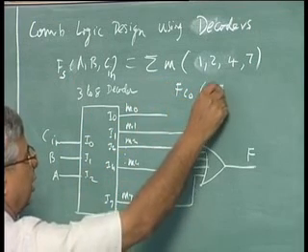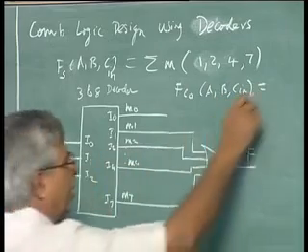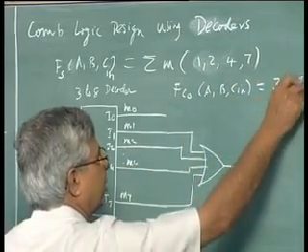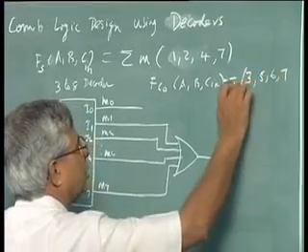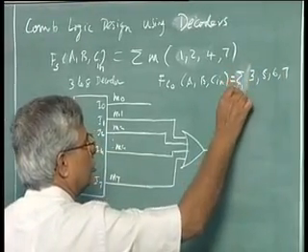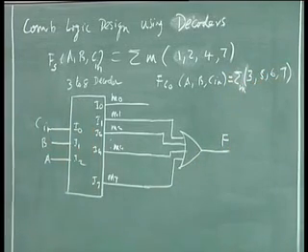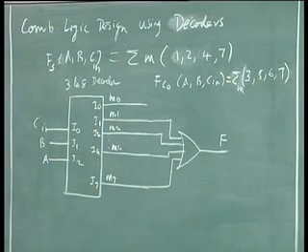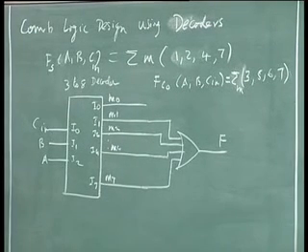of A, B, C in, or if I remember correctly, it was sigma 3, 5, 6, 7. Is that right? These are the minterms for which the output is 1 for the carry. So I can combine them. This now requires M3, M5, M6, M7.